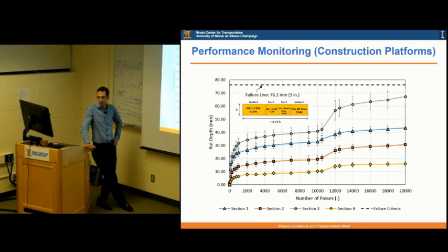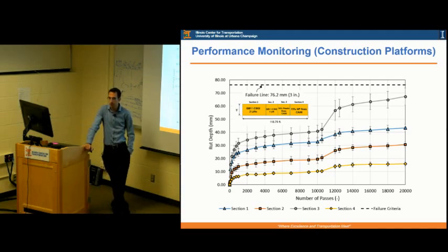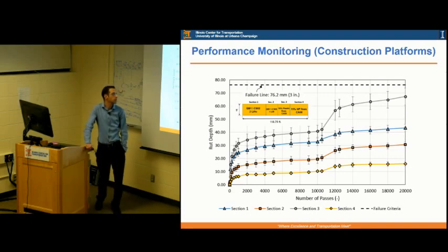So how the slopes are looking, if you think about that, the one left is, let's see, section 2, that's the second from the bottom, right? Yes. But what happens on the rainy day also, the slopes are going a little higher there, and then slopes are stabilizing, the accumulation slopes. So it's hard to tell again, but nevertheless, overall, the rut depth is more uniform and more shaken down, less accumulation of rutting. And actually, that's probably easier to see if you move to the HMA sections.